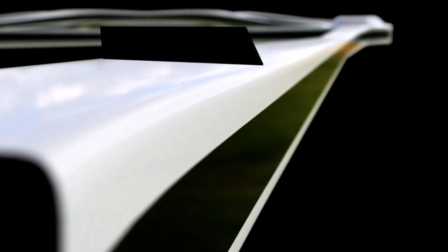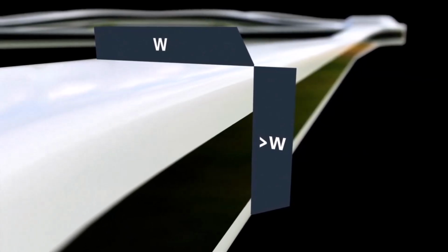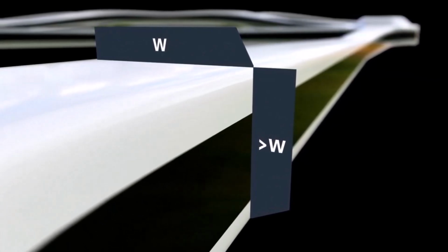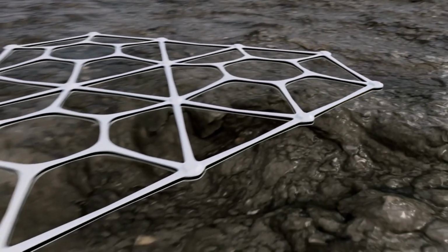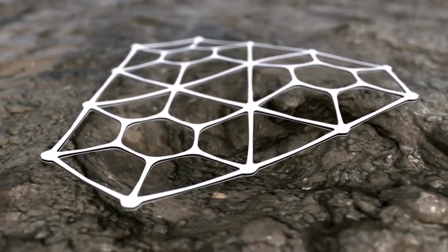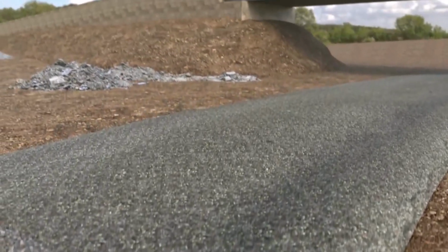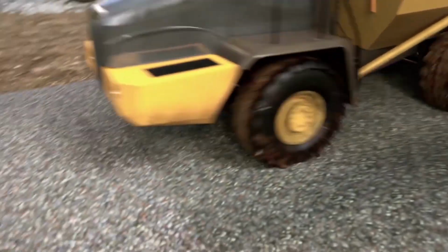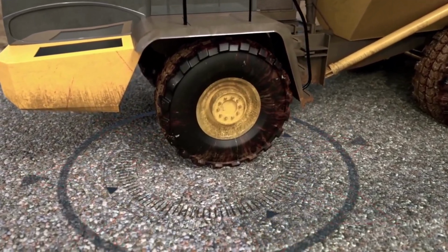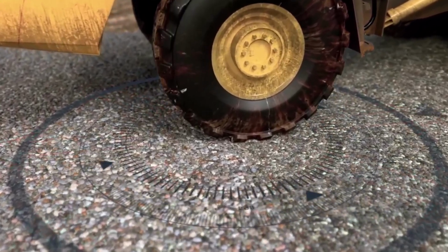The high rib aspect ratio allows more effective confinement and mechanical interlock with aggregate particles, enhancing overall MSL performance. The open floating hexagon allows for greater compliance and improved aggregate confinement under compaction and repetitive loading. Increased number of bearing surfaces provides improved performance of the GeoGrid aggregate layer by resisting radial displacement of the aggregate under load and protecting the underlying subgrade.